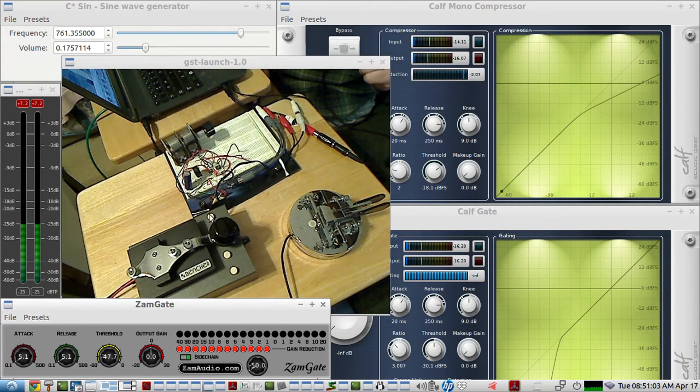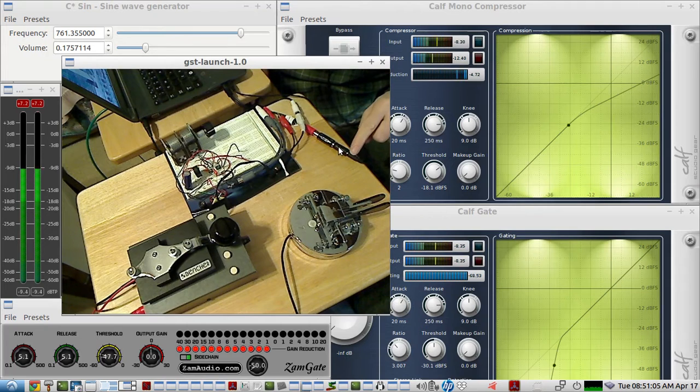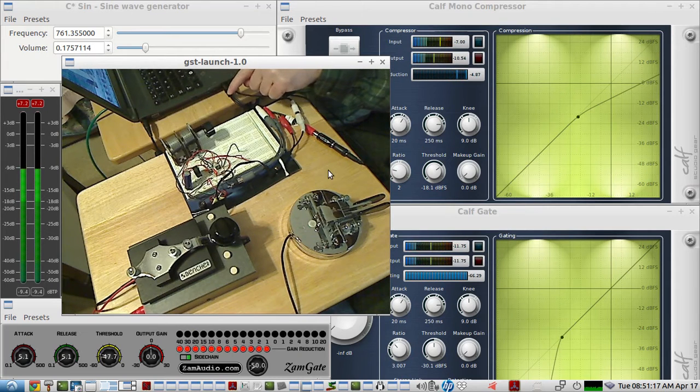And we went over the microphone here using the 2 adapters. You must have that stereo to mono in order to have enough of the voltage getting to the condenser mic. So you can use both the microphone and the Morse code in this system going into one mic jack. Since it's a stereo mic jack, we just split the left and right to do for different purposes.